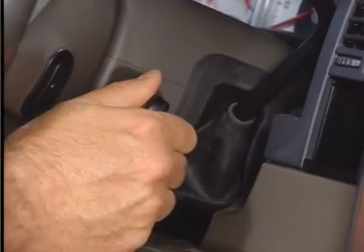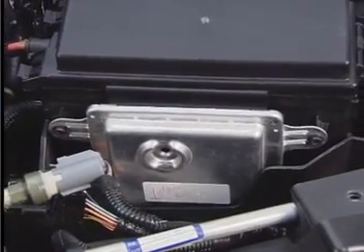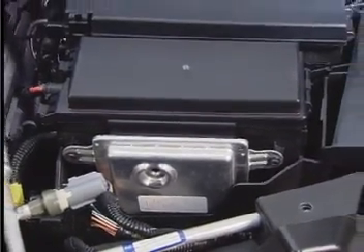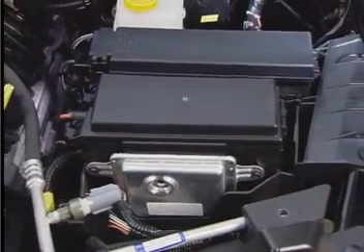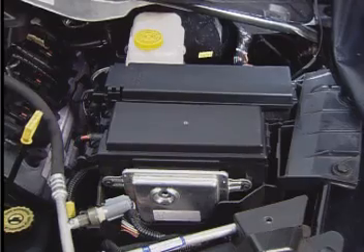Unlike the CAN-B bus, CAN-C is only active when the key is on. When the bus is active, the central gateway needs to receive responses at regular intervals from CAN-C modules, or it will report them as not responding. The voltage pulses used by the CAN-C bus to create bits for messages are different than those used by CAN-B.